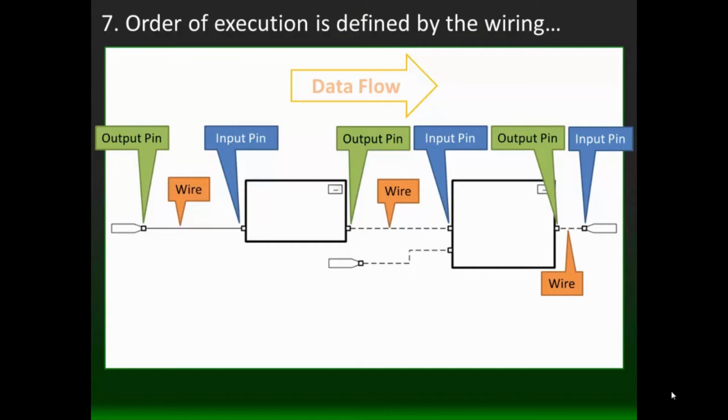So the connecting lines are called wires. A solid wire, of course, is a non-binary value, or rather to say it's an integer, single integer, double integer, floating point. A dash line is going to be a digital or binary wire. So dash lines have a state of 0 and 1. Solid lines can have a variety of values.